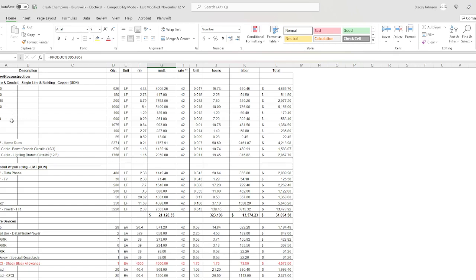Okay, and so we break that down, all the wire, all of the conduit totals by length, and of course we use a cost book to give us the material cost for the wire and the conduit. Now, rest assured that if you use a cost book that's very accurate like we use Craftsman, well, our material cost for the wire and the conduit is going to be 5% within local pricing. So, not 5% within what your supplier is going to charge you. Okay, so that's a thing to think about too.